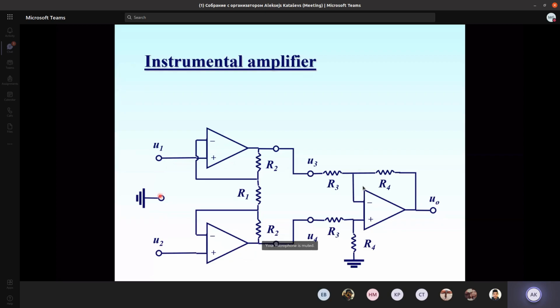So it's actually the heart of every biological signal or biopotential measurement device, or any measurement device generally. An instrumentation amplifier allows us to measure the voltage difference between two arbitrary points, independent of whether the points or the source are connected to the ground or not. And for human biopotential measurement, that's exactly what we are looking for. We are going to measure the potential difference of voltage across different points over the body surface. So this is an instrumentation amplifier.